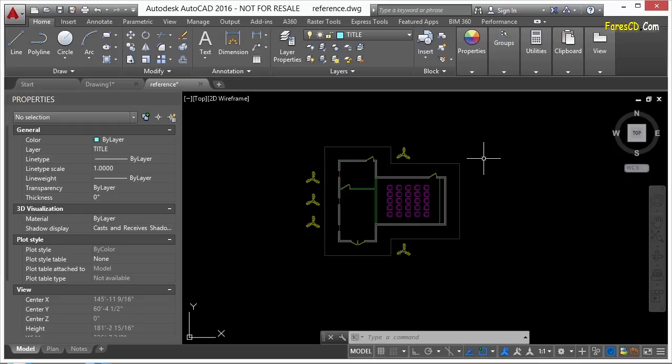Now it's good CAD practice to have each of these designs created and managed in their own CAD file. And then when it's time to create your drawing, you simply reference these drawings and annotate them as needed. You can also reference things, not just CAD files, DWG AutoCAD files, but you can also reference files like a PDF, a DWF, a JPEG, or TIFF file. These files could contain aerial views of the property or logos, title block information for your cover sheet, things like that.